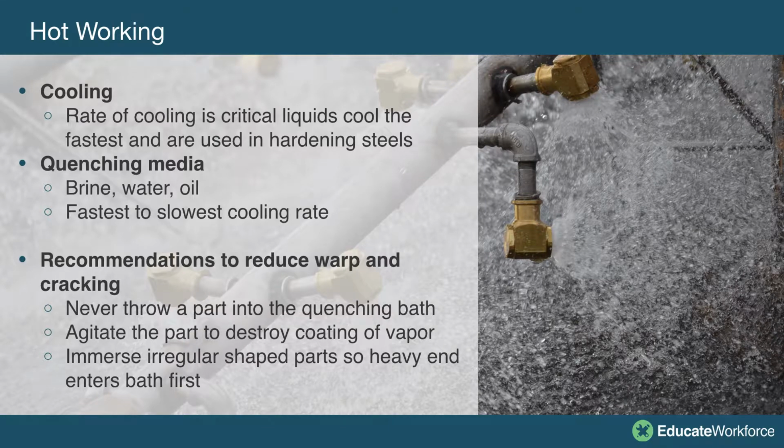Cooling. The rate of cooling is critical, and we control the cooling rate by the type of liquid we use. The quenching media, as we discussed earlier: brine, which is salt water, cools the fastest. Water is the second fastest, and then oil is the slowest.